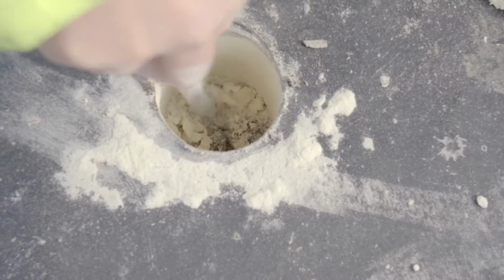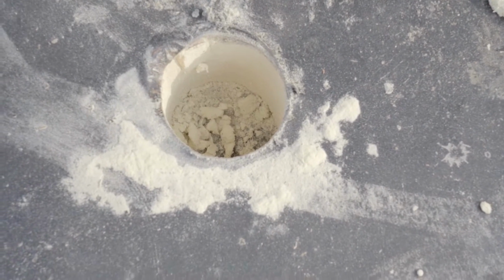So we've got a few things that we need to determine. I need to know what the existing build-up of the roof is. That's going to tell me the thickness of the insulation, because the other thing the client's asked me, and it's a prerequisite of the building regulations, is that we provide insulation on this roof to satisfy Part L. So it's important that I know the thickness of the insulation. It's important I know how much water is in the system, because that will determine whether or not I take the roof off or whether we overlay it.